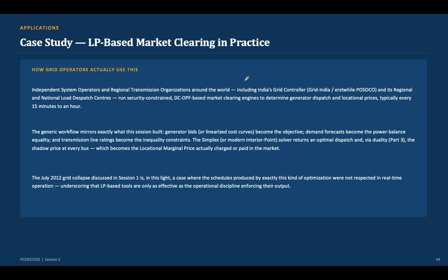So the transmission line ratings become network constraints. The optimization engine then determines an economically feasible dispatch here. The dual side of the optimization provides marginal information associated with constraints in a network-constrained market formulation. This information contributes to locational pricing. The important idea is that optimization is not merely producing a list of generator outputs, it is simultaneously balancing economic objectives, demands, network limits, and other operating requirements.